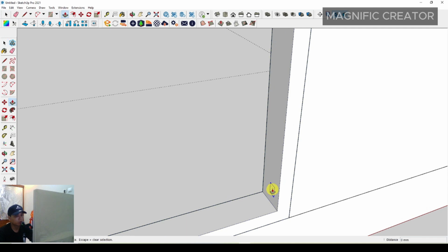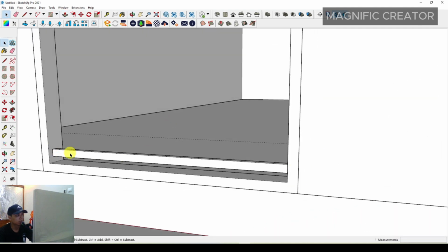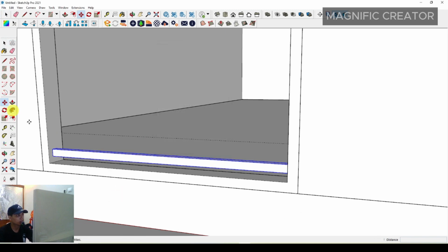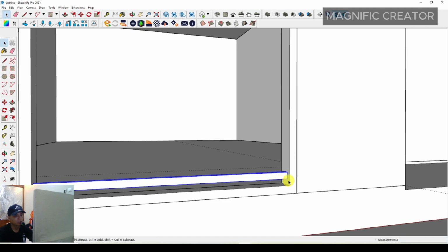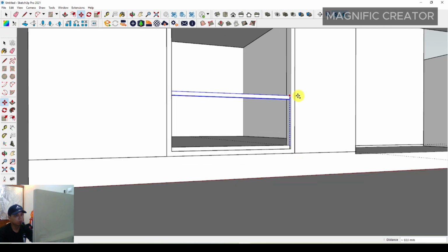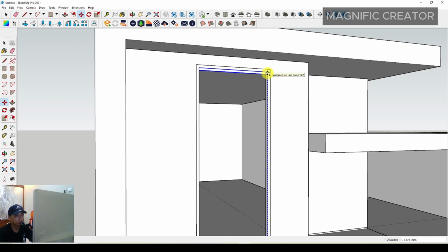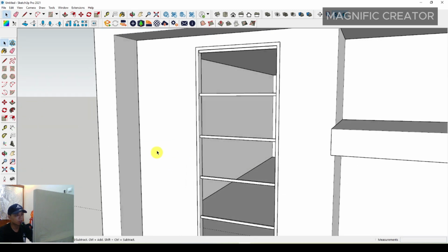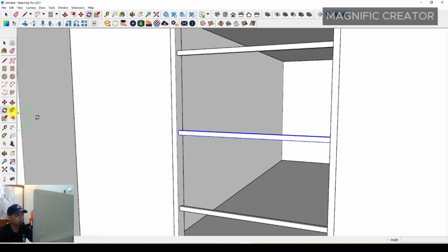And then you can make a divider frame, right? You can make a divider frame right here to make the house look more complex and realistic. And you can duplicate it. Then click and press Control to duplicate, and just click on this end point and set 5 slash and press enter, right? Then you can rotate and copy. You can rotate and duplicate with this tool.